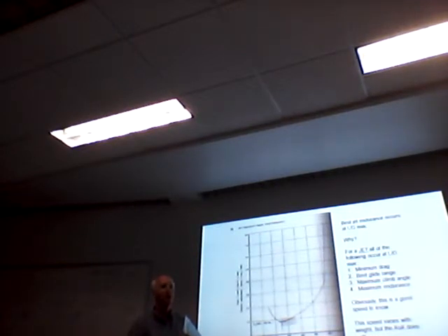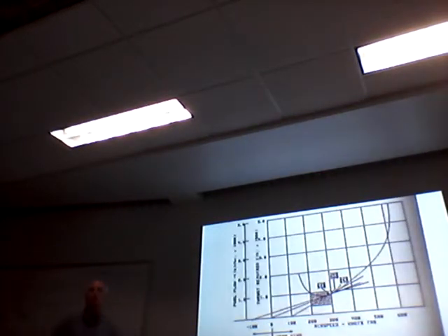You're at the max climb angle airspeed. You want to go to the max rate airspeed. Which way is that going to go? Higher or lower? Higher. Max rate is always higher. Remember VX, VY? VY is always a little higher. Rate is always higher than angle. That's true for jet or prop.